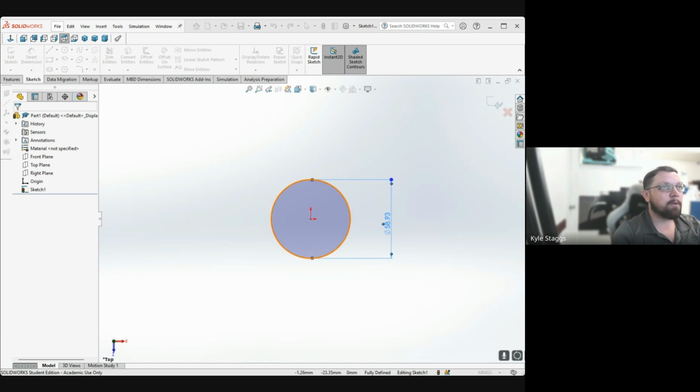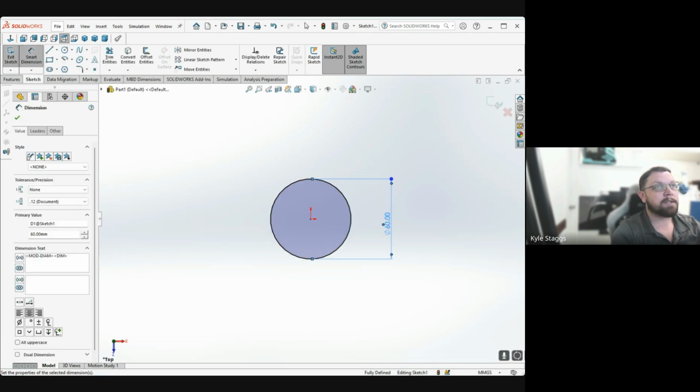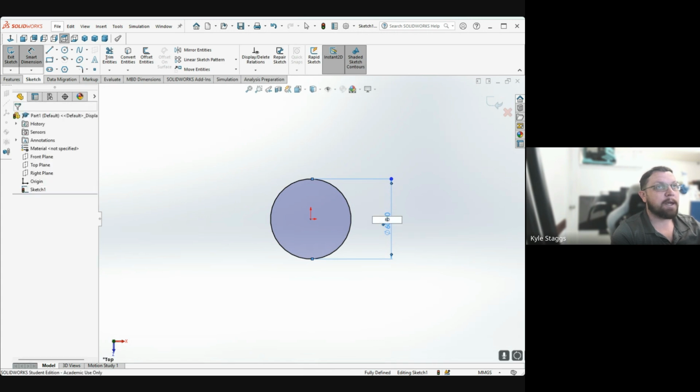This value we're going to set to be about 60 millimeters, and that's the default unit. You can also enter, and this is an important thing to understand, 2.5 IN for inches, and it'll convert it to whatever your system is. So you can enter multiple different units so long as you have the abbreviation right. But I'm going to leave this at 60 millimeters.